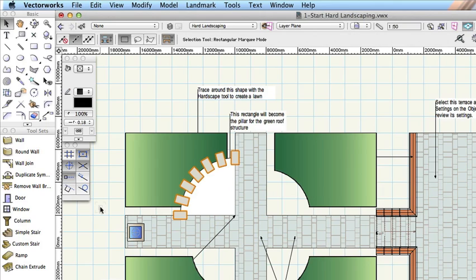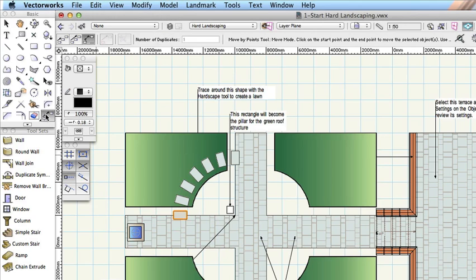Use the Selection tool to select the arc and then delete it using the Delete or Backspace key on your keyboard. Notice that the first and last symbol instances have been centred on the start and end of the arc. Use the Selection tool to click on one of the end symbols. From the Basic palette, click the Move by Points tool and then choose the first mode, Move Mode. Ensure that Object Retention Mode is not clicked and that only one copy will be made. Move by Points can be used to copy objects, but on this occasion you'll just move the objects.